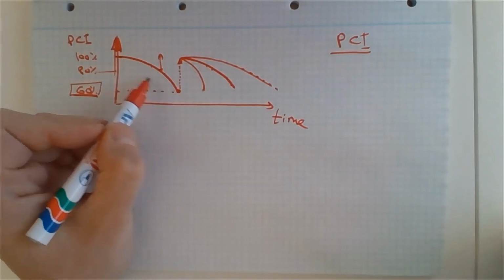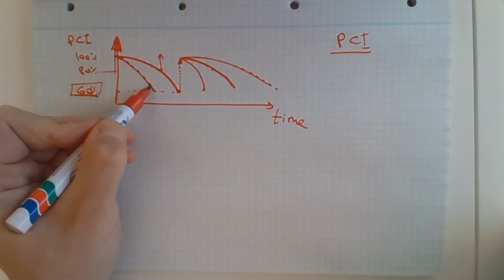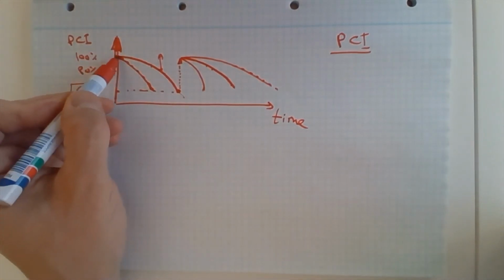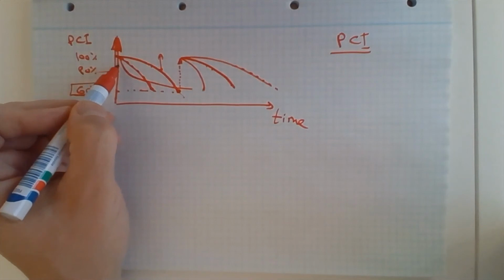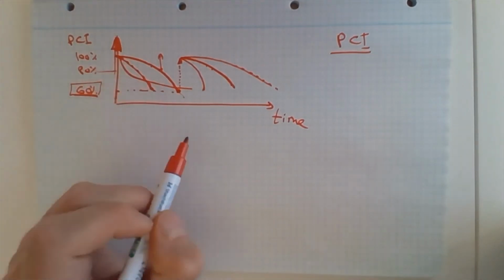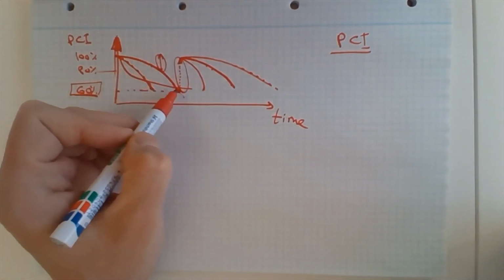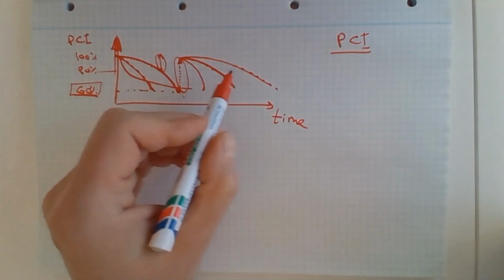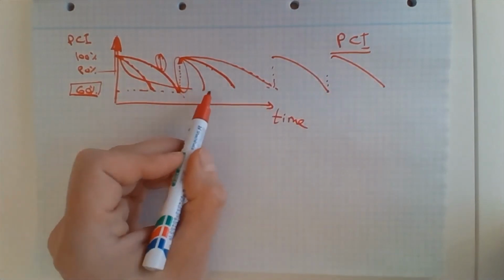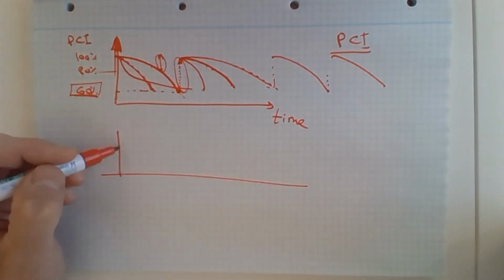We can also assess design methods, because if of two new pavement designs, one of them is deteriorating faster than the other, it means that there was something wrong with the design or with the construction. The shape of the curve could also indicate the quality of the materials and the quality of the construction. And of course, we can also check the amount of money that was required to increase the PCI value, and check over a very long period of time if one strategy for maintaining the pavements is more cost effective as compared to another.